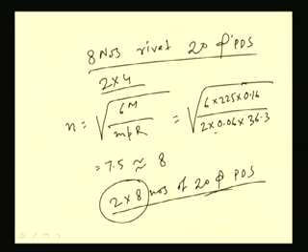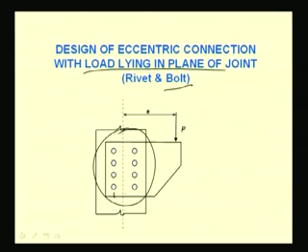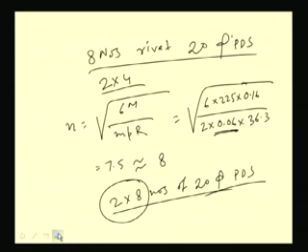Now, this 60 mm has been considered from here. So, if we see, this is the 60 mm, right. So, in this way we have calculated. Now, let us go to the detailing of this. So, 16 rivets are placed in 2 rows. So, 8 rivets are placed in 1 row. So, let us place and let us find out the details of those.